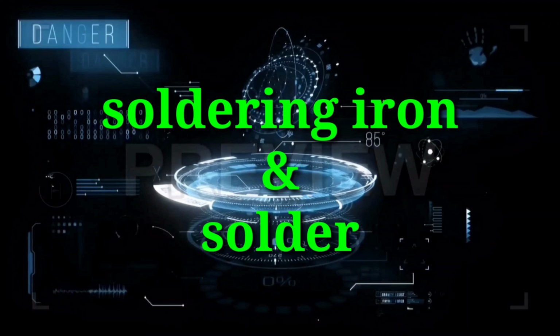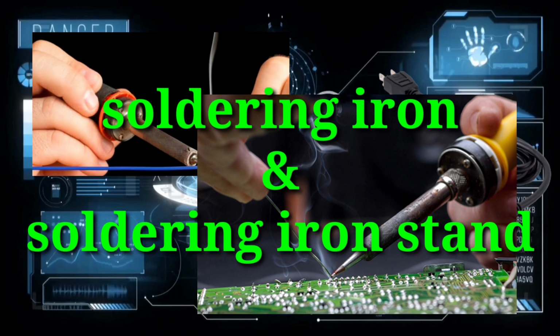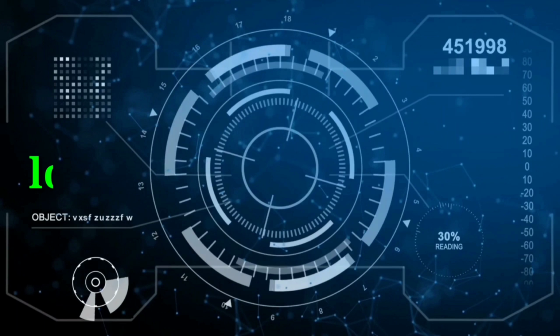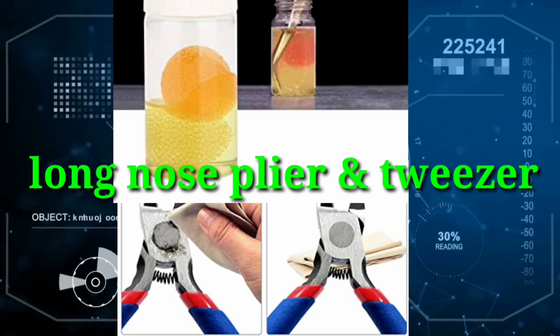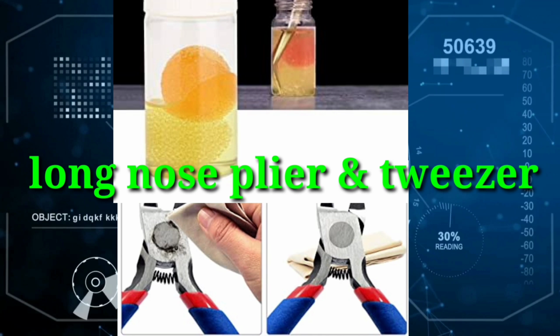Soldering iron and stand. Always use a soldering iron stand when you aren't soldering to avoid burns or damage. Long nose pliers and tweezers. After using the long nose pliers and tweezers, clean them properly with cleaning oil and cloth to keep them from becoming dull and rusty.